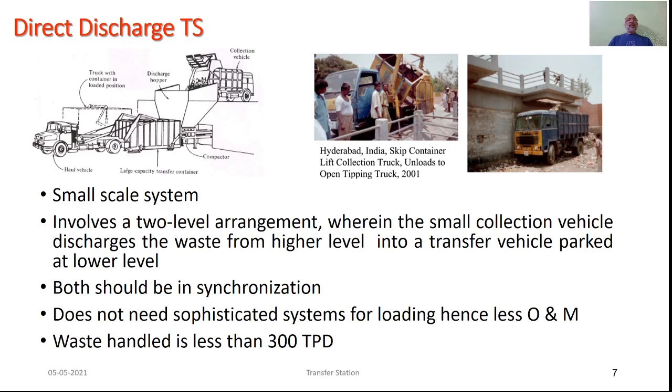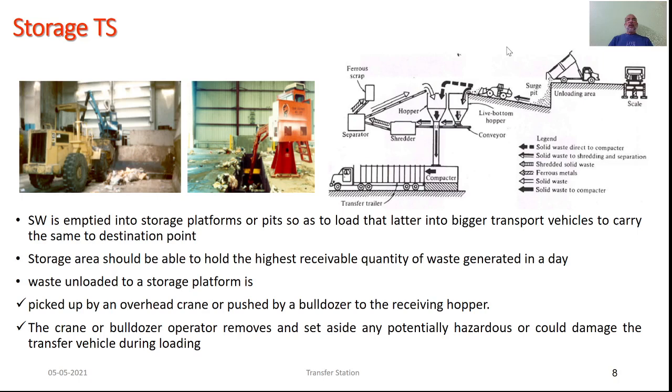Another kind of transfer station is the storage transfer station. So the way you see here, the solid waste is emptied into the storage platform or pit so as to load that later into bigger transport vehicles to carry the same to a different facility.